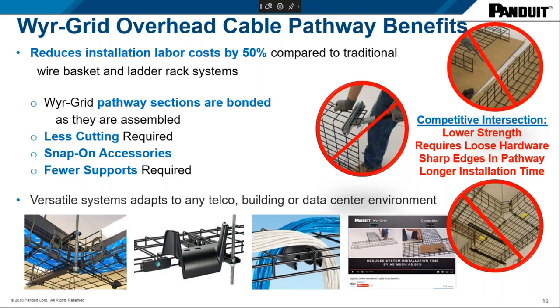Another feature that we do have in our basket is that we do have larger openings on the basket itself. And what does that provide? So with the larger openings, you don't have to do that extensive cutting. So let's say you're going to install some sort of waterfall, some sort of way to exit down on the cables. We actually have waterfalls that easily snap into place as we're showcasing here. Even with our openings themselves, you can actually have a cassette go straight through the opening with no cutting required.